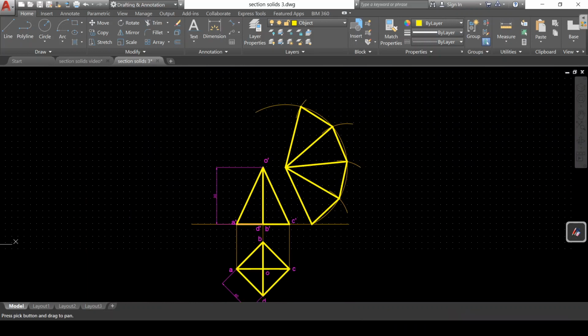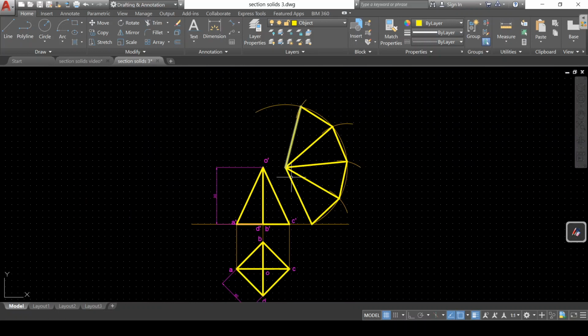Suppose we open it from OA. So this will be our OA, and then the next B, C, D, and again A, because we are tearing it and we are unfolding it. So this will come twice at the end also. And then when we want to make this solid, we will fold it along these fold lines and join these two connected. So that is how the concept of development is utilized here.